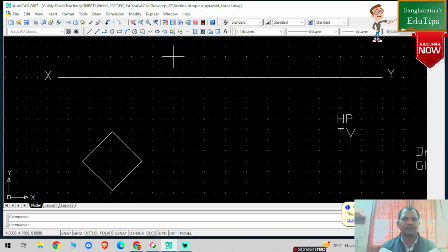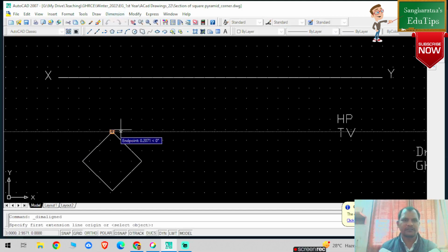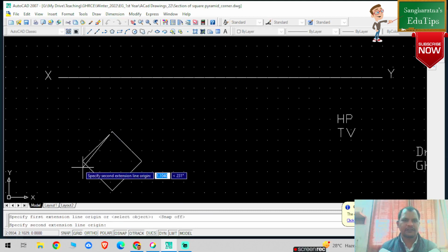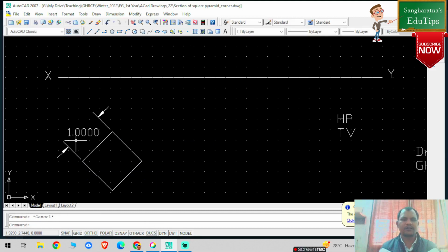You can check the length as well, using dimensions, aligned. Select this particular dimension and click on snap, from this particular line to this particular point. So this is basically one AutoCAD unit.